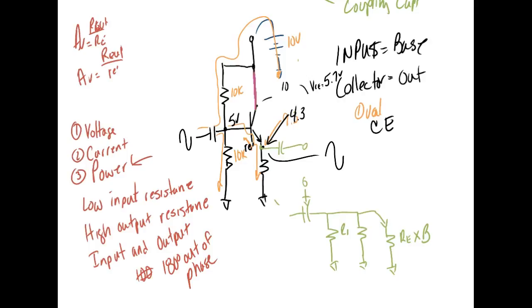So I don't get any current gain out of this guy. But man, it's easy to calculate. I mean, good gracious. Because these two resistors over here are probably going to be pretty close to the same size to set this up to be what we call class A. Normally this resistor down here might be just slightly bigger because we would like this right here to be sitting at exactly half of VCC. If we make them the same size, it's going to be 7/10 of a volt less than half, right? You understand that? So we can't get voltage gain out of this puppy.